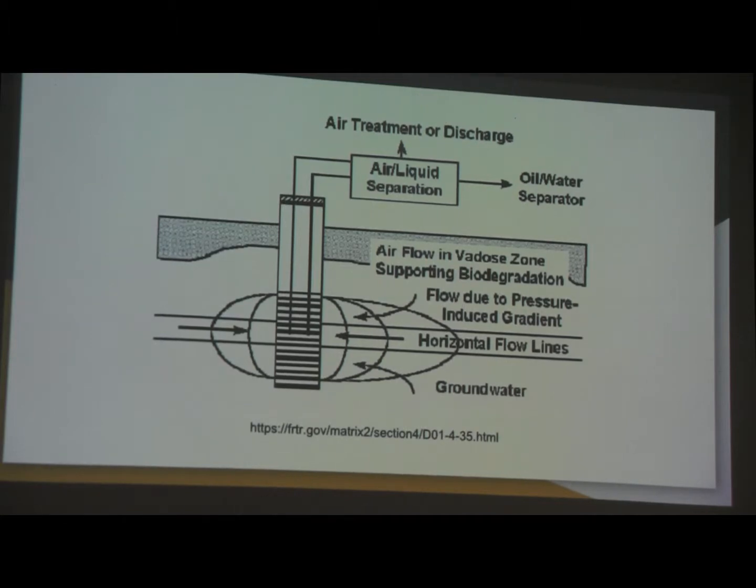And once those are withdrawn, bring in the soil gas, this is what's easily converted to the biovent to treat the VOCs that may be present there. I don't think the injection well is present, but that's where you're getting these horizontal flow lines and the pressure-induced flow lines. And yeah, I think you kind of get the pattern now. It's going to go up. You have your treatment methods up top, but no water is getting removed and no dirt's having to get dug up. It's just most of the contaminants getting drawn out.